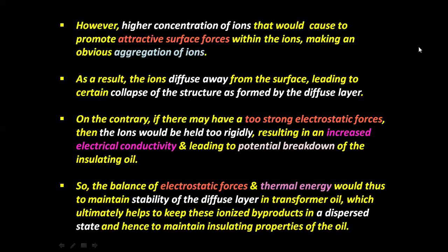So, the balance of electrostatic forces and thermal energy maintains the stability of the diffuse layer in transformer oil, which ultimately helps to keep these ionized byproducts in a dispersed state and hence maintain the insulating properties of the oil.